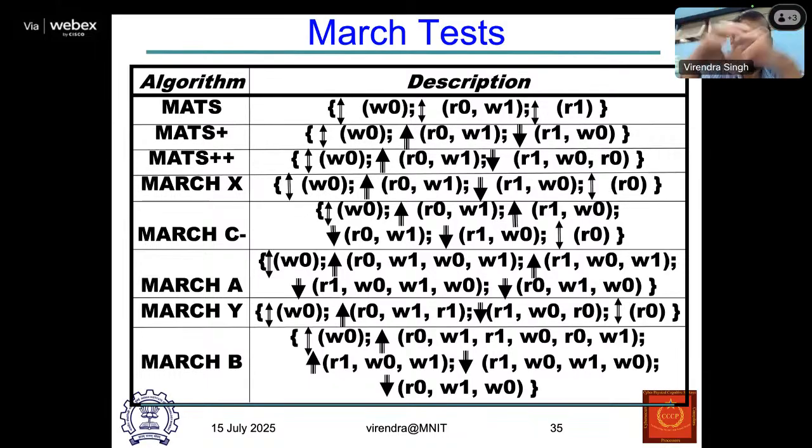So these are the four reduced fault models we developed, and we have developed at least one test so far that goes through three marches: March M0, March M1, March M2. In March M0 we are writing the value 0 everywhere. In March M1 we are first reading the value of that particular cell and writing the value 1.